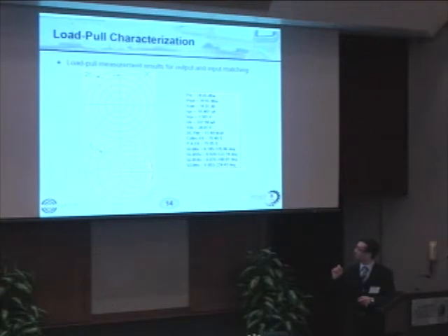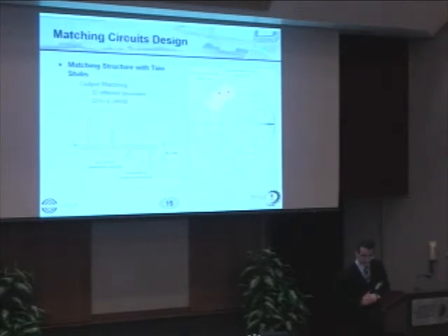The figure on the bottom shows the fundamental matching, and with this result, using again a 10 watt transistor, we can achieve an efficiency of 78.5% at 2.45 gigahertz.